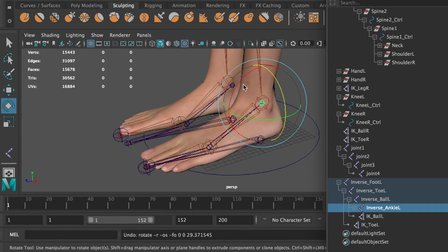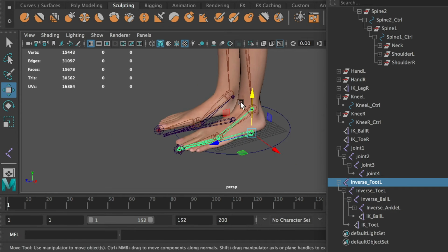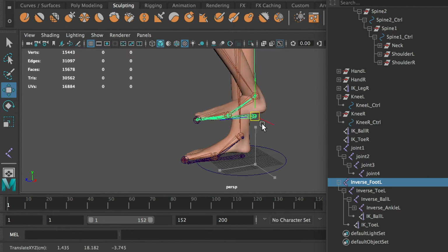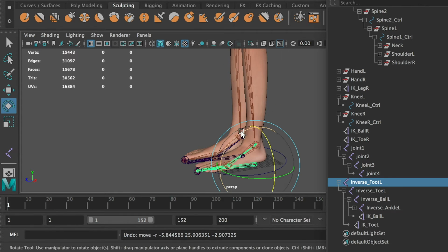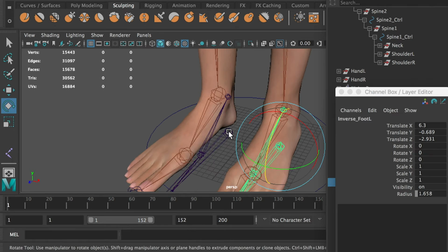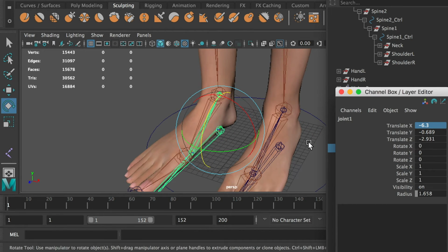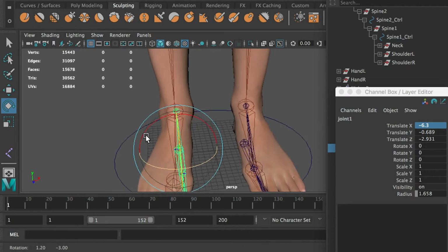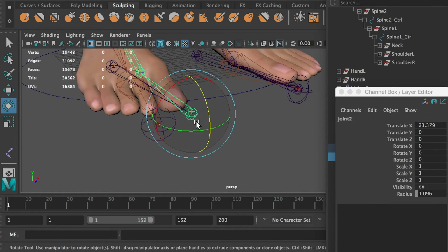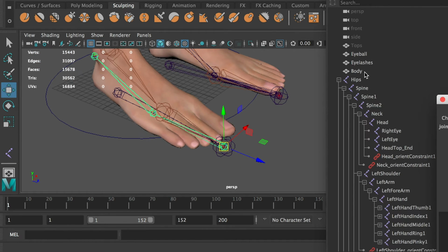After applying the reversed foot rig, both the ankle joint and the reverse ankle joint aren't able to move the foot anymore. Instead, the foot joint will do the job. Now, you can put the same translate X value on the reversed right foot joint and move it to the right foot. Following the same procedure that we did on the left foot, we will snap the reverse toe joint to the toe joint and rename it.